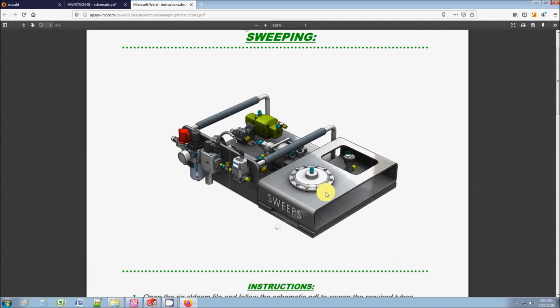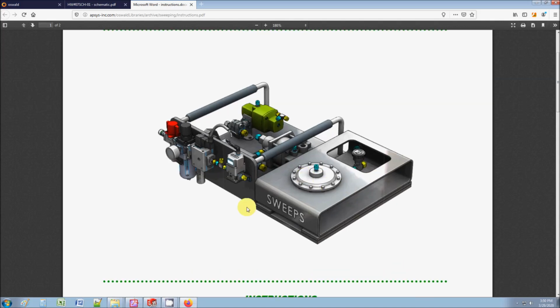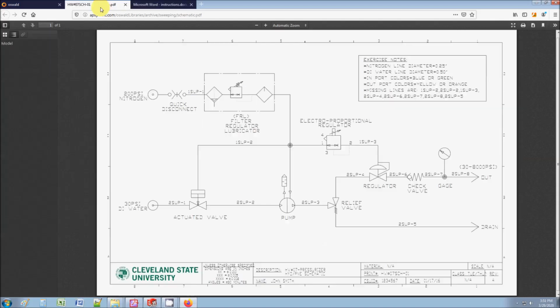This is a pressurizer, okay? It's very simple. This uses a PLC to control the pressure, but based on what you type, it's going to energize and control the system to deliver pressure on the outbound, as you can see with the provided schematic. So this is an interesting system because you have a pneumatic system controlling a hydraulic system.